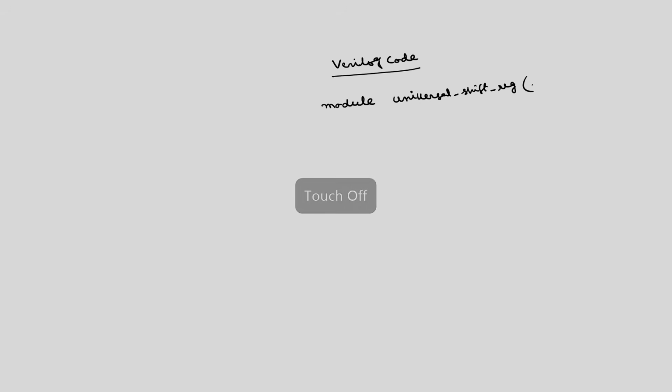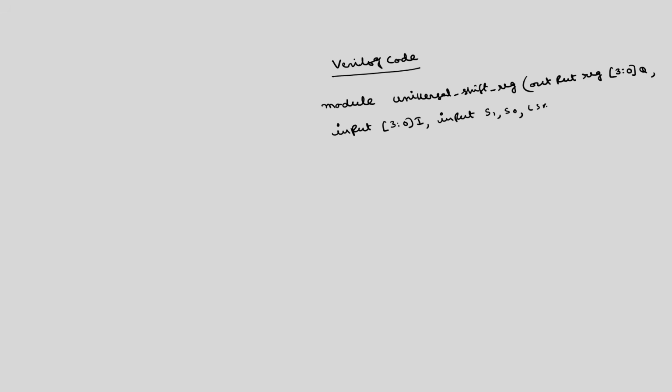First I will write output reg [3:0] Q, input [3:0] I, input S1, S0, LSB in, MSB in, clear, clock.